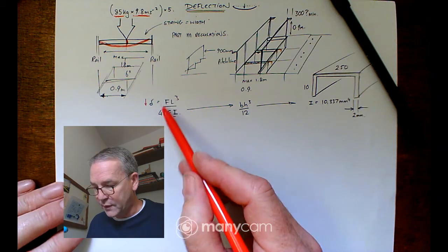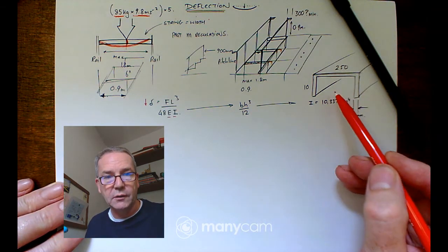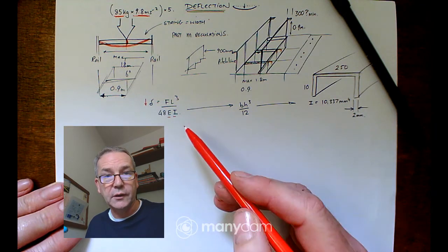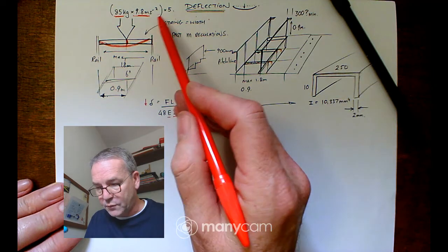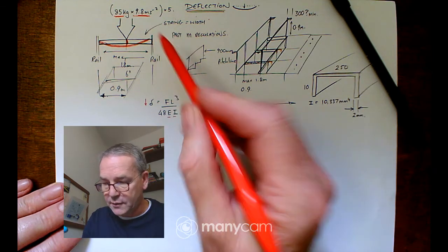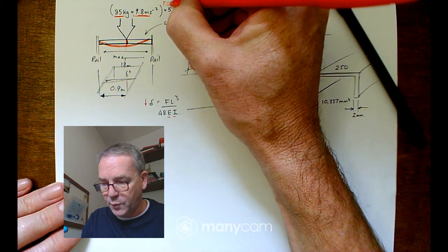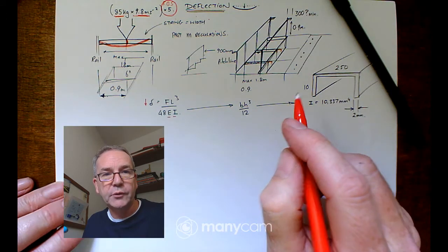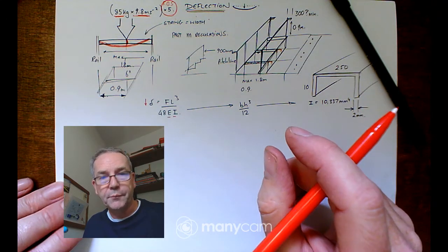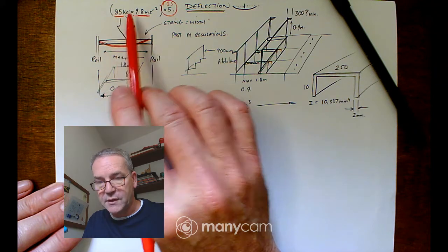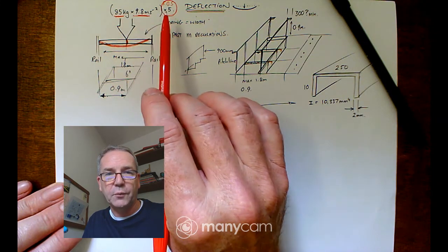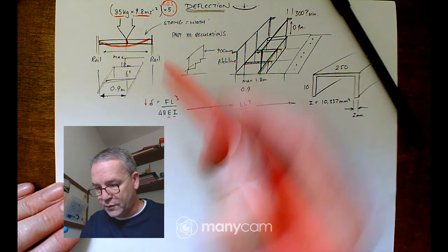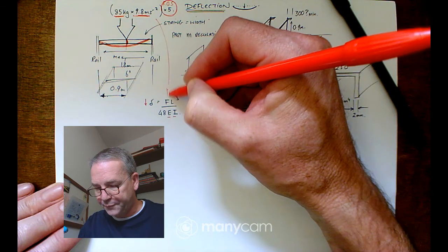So we will redo this calculation for the inertia and make sure it's done in meters, and then we'll continue everything in SI units. Now I've done some research, and the suggestion is that for a factor of safety, I think this is a bit high, but one of the websites said that it should be able to cope with a load 5 times the maximum. So if 5 times the average is 85, if you were more than that, going for 5 times as much, we should be well in. So we're going to use that for our force.